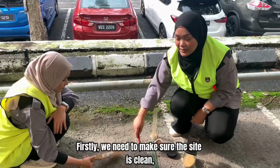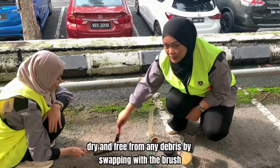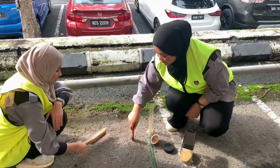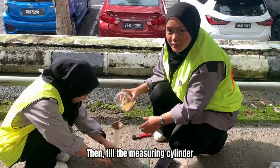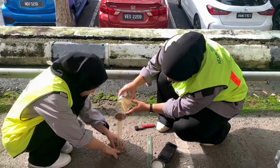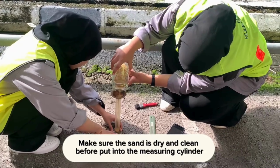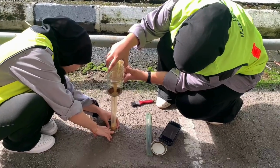Firstly, we need to ensure the site is clean, dry and free from debris by sweeping using the brush. Then fill the measuring cylinder with 25 ml of sand. Make sure the sand is dry and clean before putting it into the measuring cylinder.